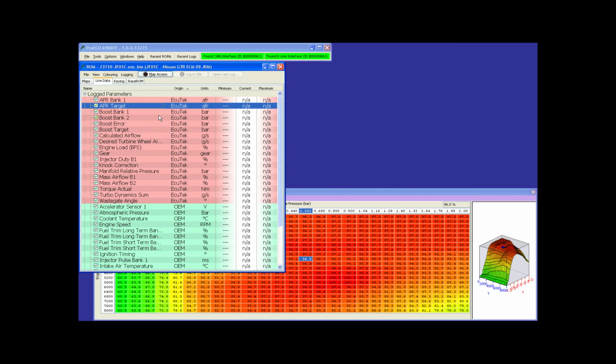So we can see here, a quick skip through them: AFR, that's the AFR from the factory AF sensors. It's got a certain scale factor applied at the moment that makes it read richer than the car actually runs. The car might be running 11.2, but the true AFR might be 11.1. We're going to work to improve that, and you're going to need to watch out for it if you've been using the product for a while, but we're going to put in a new rescaled, more accurately calibrated AF sensor like that on the Nissan Juke, let's say.